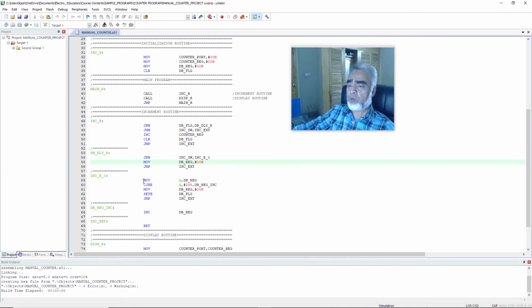So first we'll comment the first line, that is move. Here we will comment this line and replace the accumulator with the db register. We'll copy this variable from here, Control C, and paste it here, Control V. It means that we want to compare a RAM location with the number 255. Now we'll compile our program and see the result.